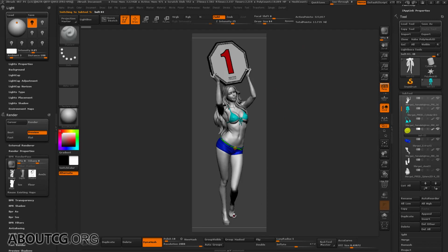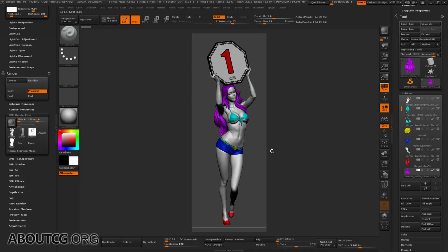At this point, we can turn on occlusion and turn on shadow. We don't need 3D, so turn off 3D. Set the sampling value to 7. Okay, let's render directly. When the sampling value is set to 7, you can see that the rendering speed is not very fast. Everyone needs to wait patiently.